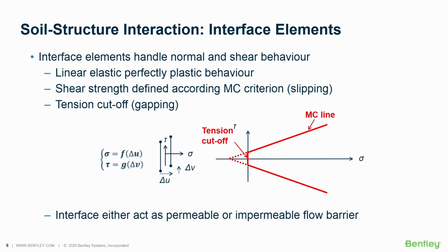They should be as small as possible, but we will limit the development of those stresses through a set of failure surfaces, which are represented on the right-hand side, delimited by the Mohr-Coulomb line for the shear and the tension cutoff for the tension part. So as long as the stress paths move within those boundaries in red, the behavior of the interface will be assumed linear elastic and considerably stiff compared to the soil. So it's in such a way that the condition will correspond to a sticky situation.